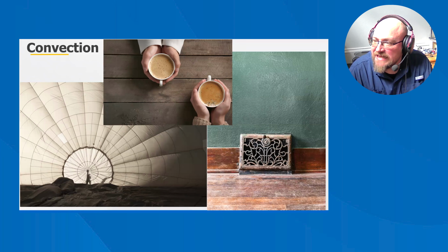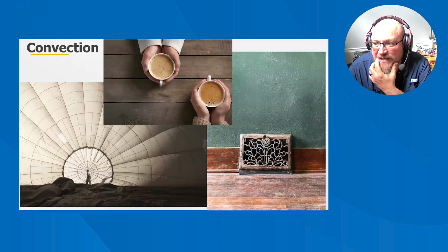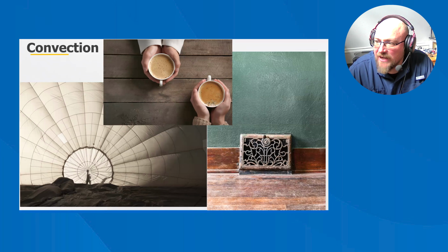The old gravity furnace heats the air. The air gets lighter and rises out of the heating system. Cool air enters the heating system and pushes or displaces the warm rising air. The warm air rises through warm air ducts or pipes, often called stacks, that are inside the walls. The warm air rises up through the building.